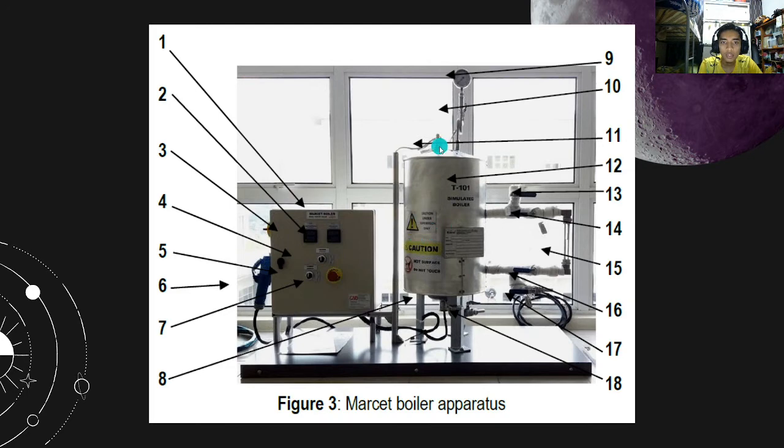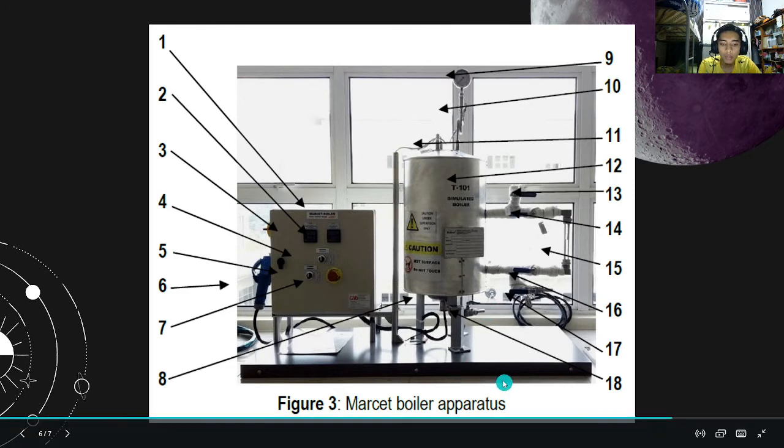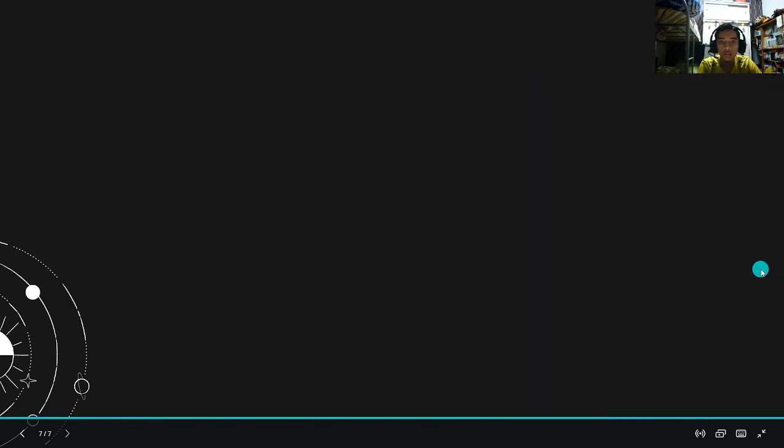Then we will open the valve at the upper side, MVB102, to release the water, and then we will open the valve at the bottom part, this one of the side glass, and the valves MVB104 and MVB105 to drain out the water of the tank. So that's it for part A.